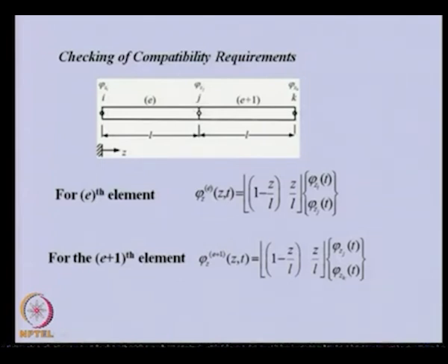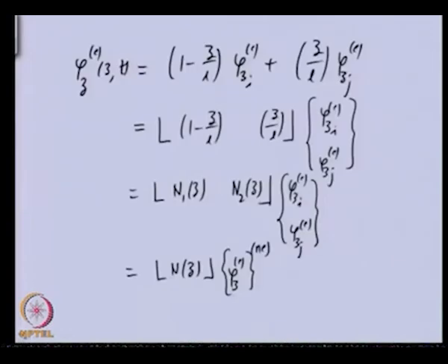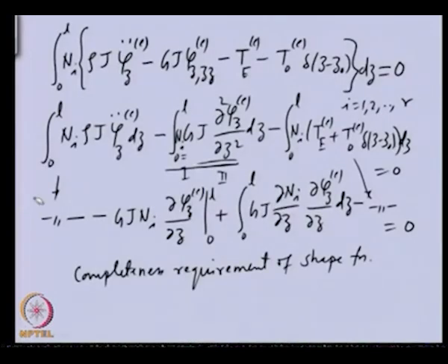So, in this particular case, if we go back to our weak formulation equation, within the integral, whatever the highest derivative of the field variable is, we need to satisfy the compatibility condition one order less. This is, I should say, the thumb rule: within the integral in this weak formulation we have the first derivative of the field variable.